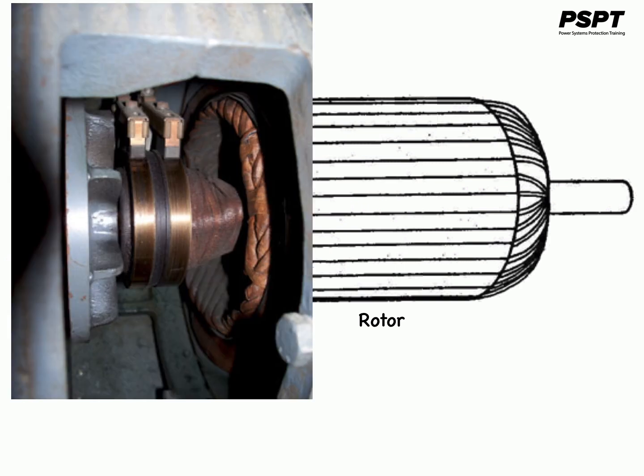Slip rings and brushes create a few problems when they are used to supply DC power to a field winding of a synchronous machine. They increase the amount of maintenance required on the machine, since the brushes must be checked for wear regularly. In addition, brush voltage drop can cause significant power losses on machines with larger field currents. Despite these problems, slip rings and brushes are used on smaller synchronous machines because no other method of supplying the DC field current is cost effective.